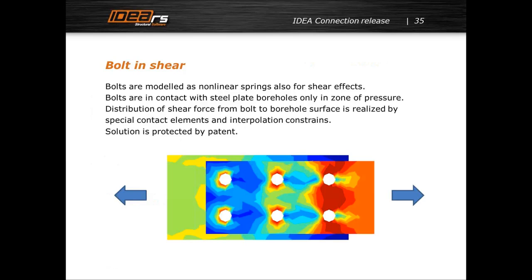Now we have maybe the answer to your question about bolts in shear. We put boreholes in our model in plates. The boreholes have the real diameter according to databases and codes.